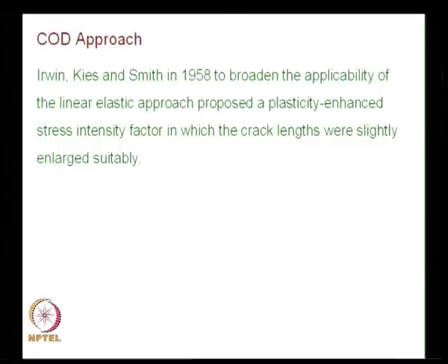What they have said is, you have to get a plasticity enhanced stress intensity factor. In this, what they had done is, we have already looked at in the context of the surface cracks. Instead of taking the crack length as A, they had taken a small extension of crack length which is dictated by the plastic deformation near the crack tip. This was one kind of an approach.